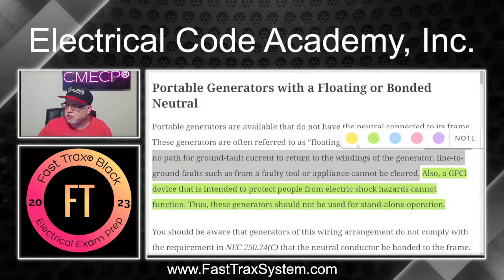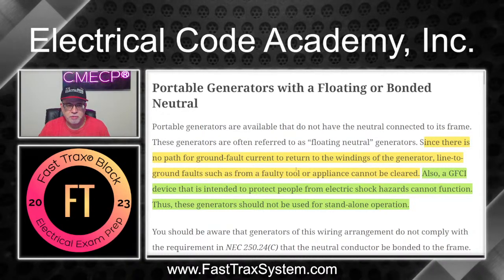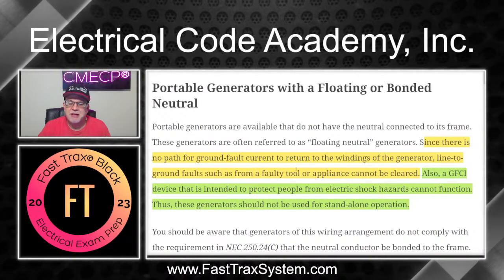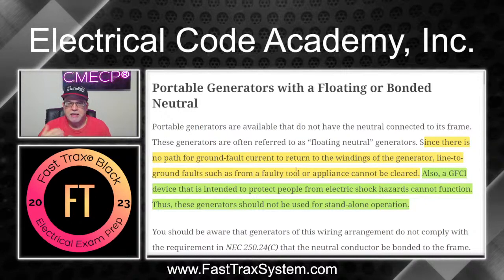They will not function the overcurrent protective device properly. Okay, so it creates an unsafe condition. So if you're still using corded tools on job sites, then again, it can create an unsafe condition if you're using a floating neutral type generator. Okay. All right.